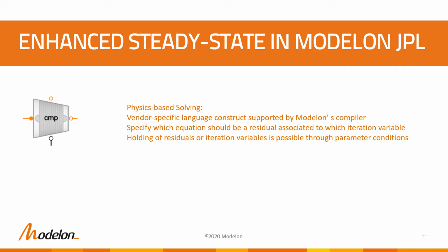Holding of residual and iteration variables is possible through parameter conditions. Adding this vendor-specific language construct is referred to as physics-based solving. The physics-based solving implemented in our libraries relies on Modelon insights about the physical properties of components and systems to achieve a structure of the system of equations that yields vastly superior numerical properties as compared to traditional automatic tearing